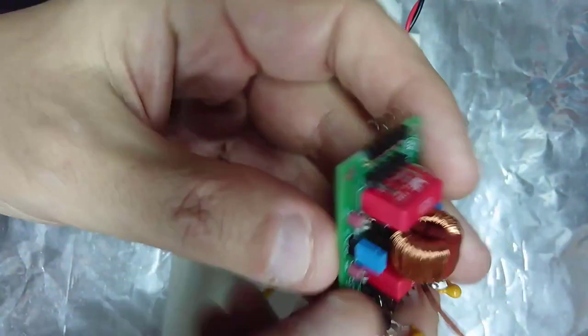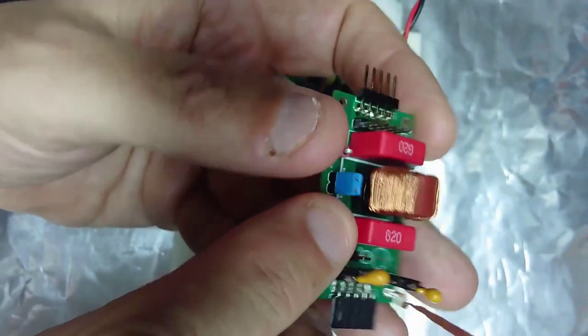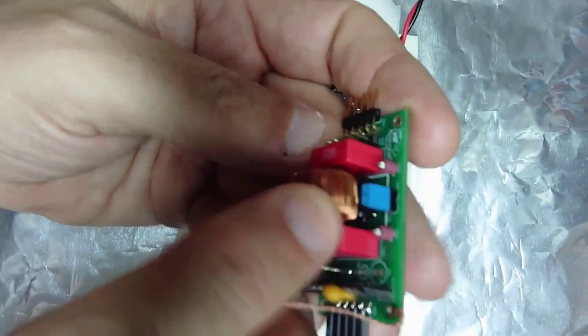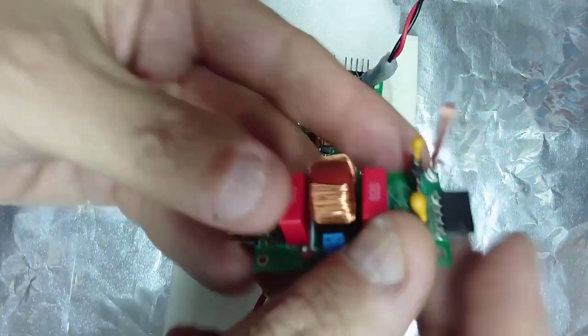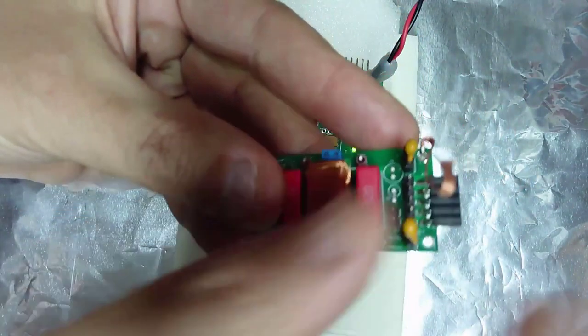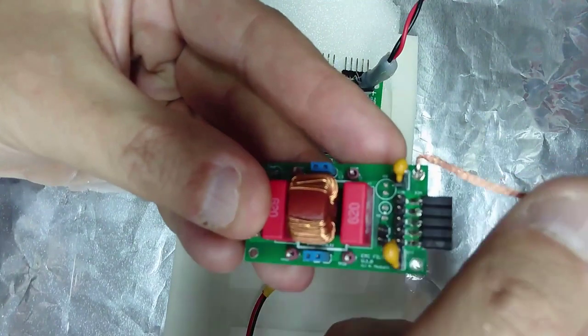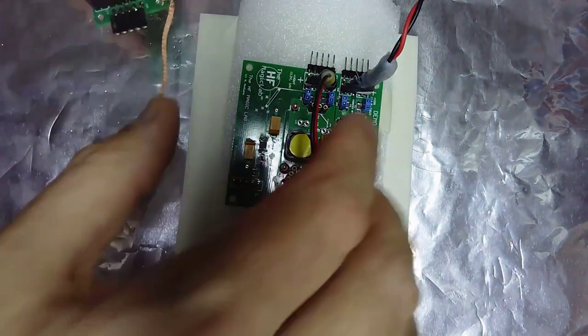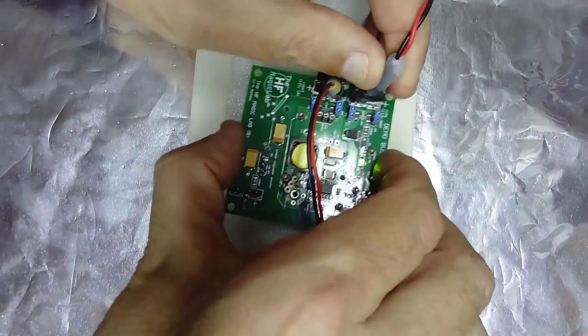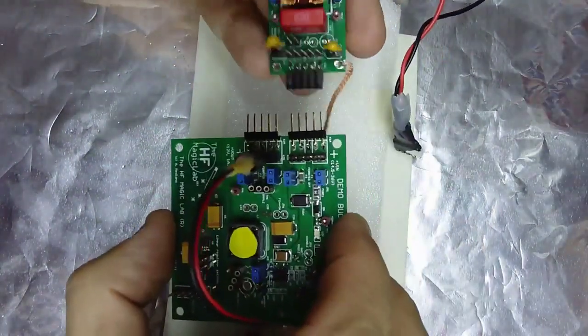So you can see here that with these jumpers, I am short-circuiting the common mode choke. So now the common mode choke is not activated and the Y capacitors will not be working because I am not going to connect the Y capacitors to the metal plate. So if we introduce the filter in place, let me disconnect. Let me connect here.